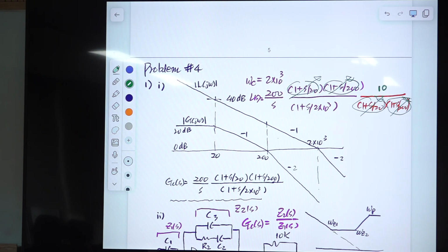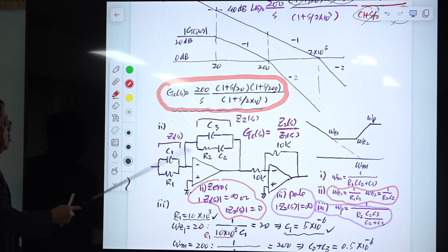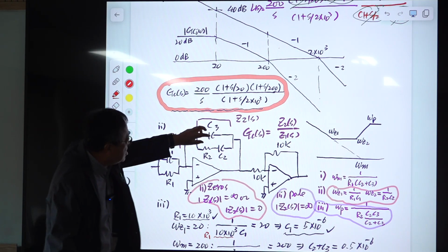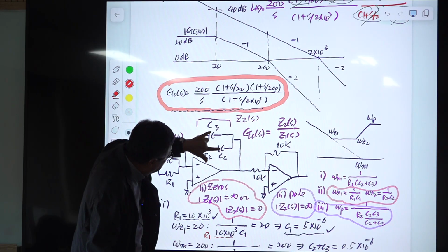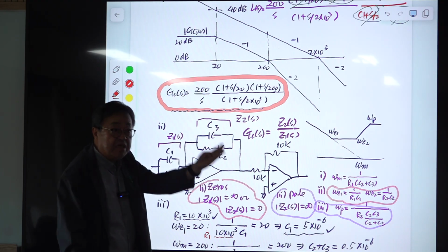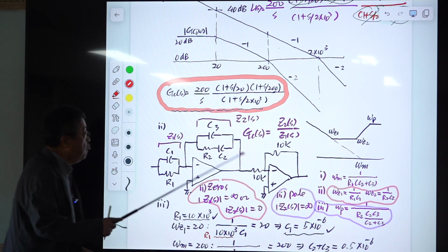So the final structure for the compensation is this one. So everything is determined. Okay, this is the circuit, all right? This is a sign changer, and there is a mixer, and you need an integrator structure. Then you should have a capacitive path. So maybe you need 2 capacitors and 3 components. With this, you can implement what? Integration and 1 pole and 1 zero.